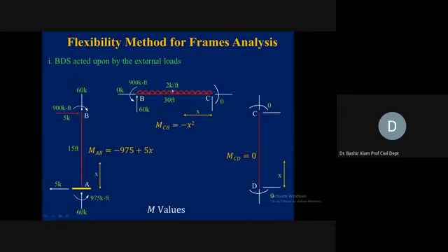Now let's put this member BC in equilibrium. So 60 in upward direction and 2 times 30, 60 in the downward direction. So here the balance coming at C now is 0. 60 minus 60 is equal to 0. So upward here is 0. Horizontal at B is 0. So horizontal at C is also 0. Summation of Fx is equal to 0.